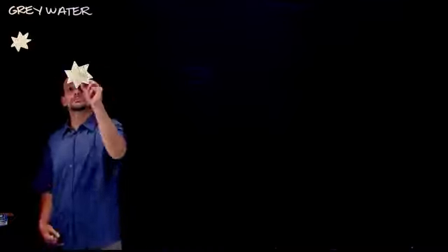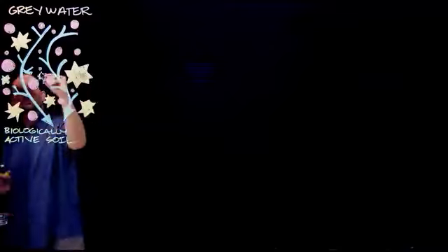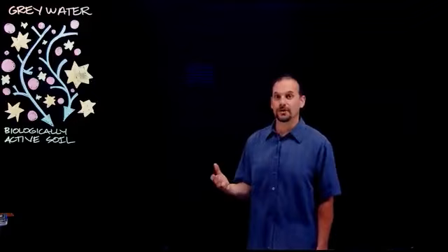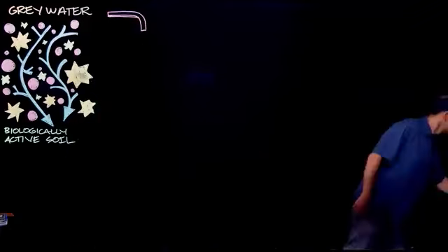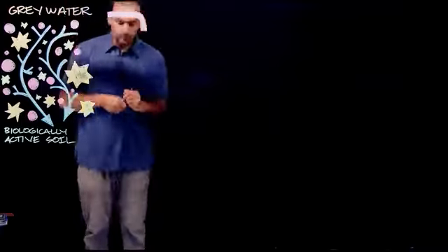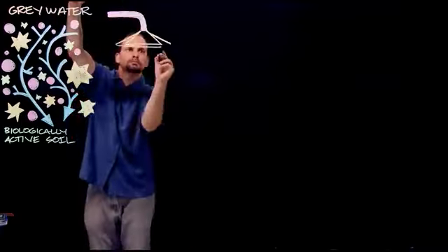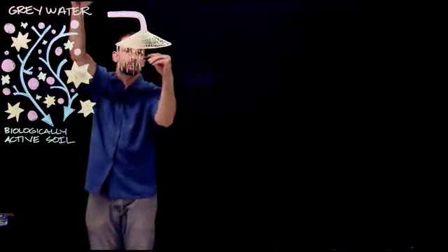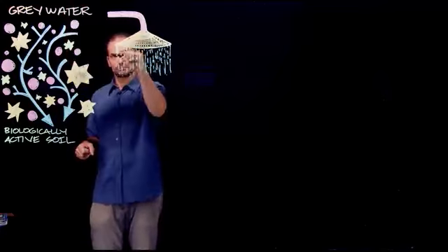So all we need to treat most gray water is for the water to contact biologically active soil. Now, the cleanest and most diluted gray water in our homes with the highest volume typically comes from the shower, bath, and laundry. The kitchen and bathroom sinks actually have pretty concentrated pollutants and may require a grease trap, so they're not really the easiest sources of gray water to recycle and may be better categorized as black water.